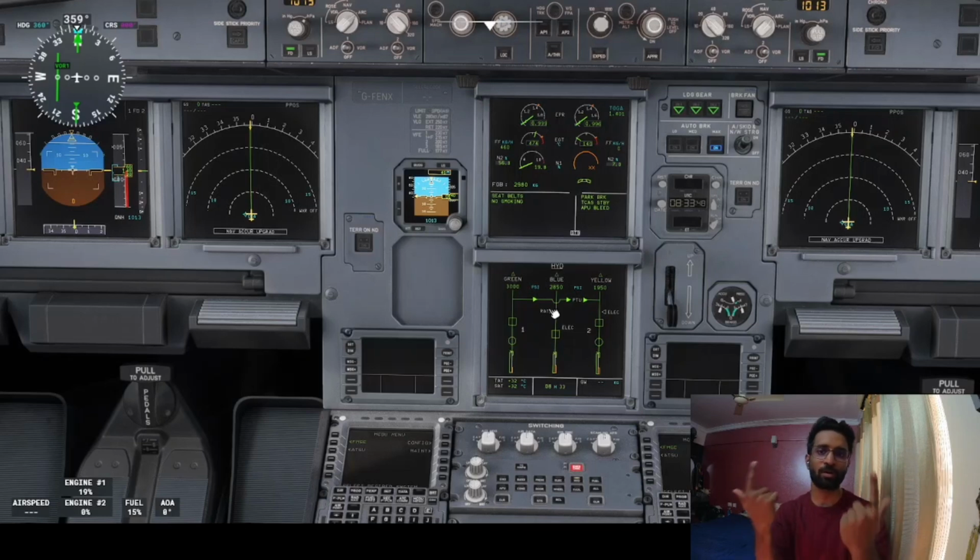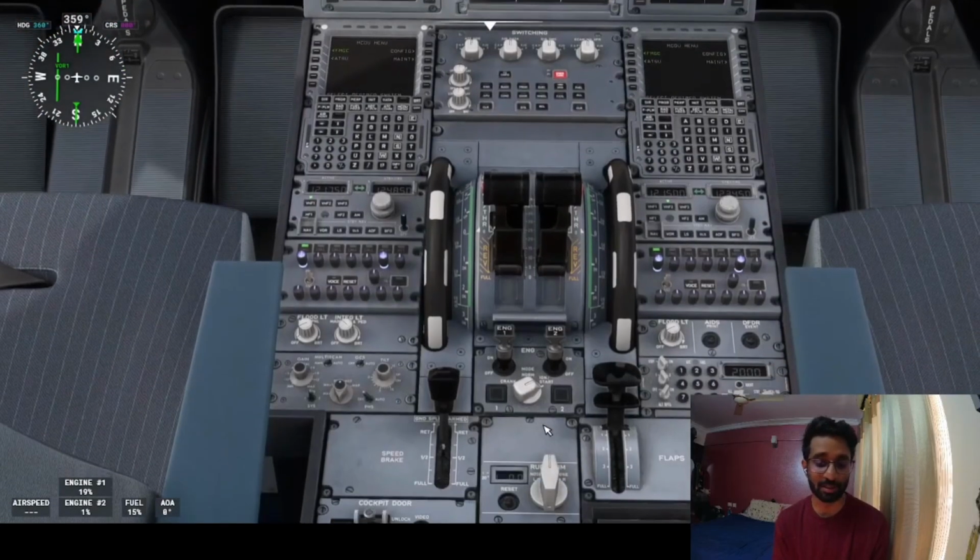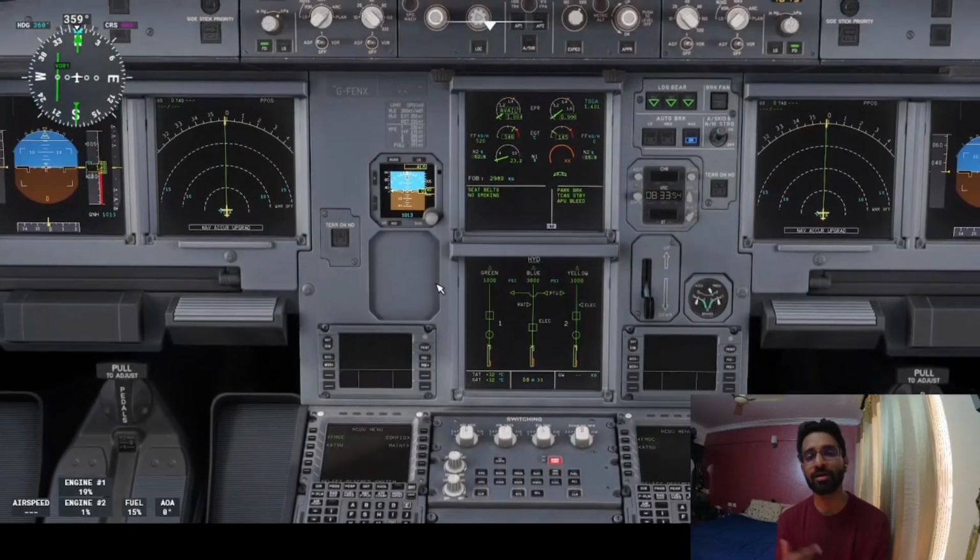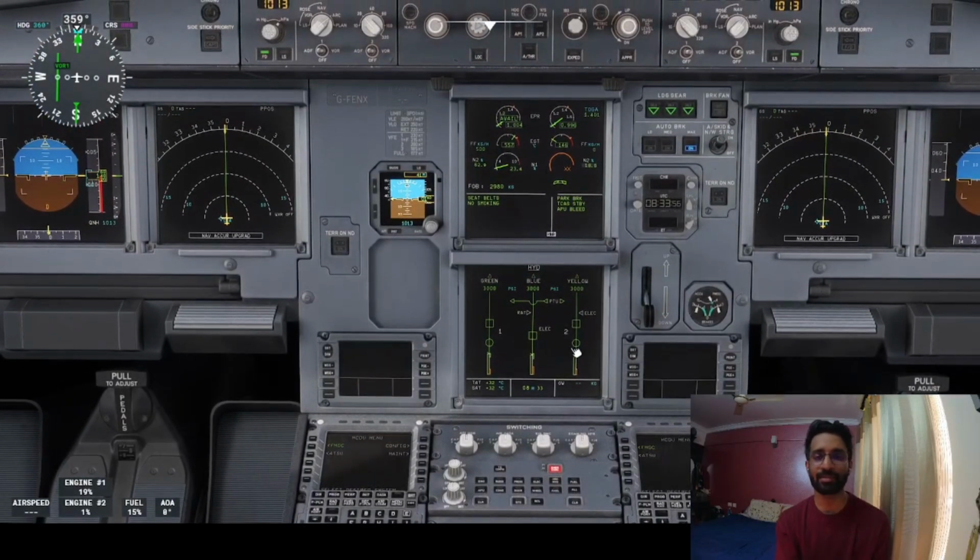Now there is no longer a 500 psi pressure difference between green and yellow. So the computer needs to check if the PTU is functioning, right? It's a very important component. So at second engine start, once the master goes on, the PTU will do a self-test to ensure that the PTU is running. That is why the PTU is working now. Even though 500 psi is not there, PTU will work when the second engine goes on, just to do a self-test. Hope that is clear.